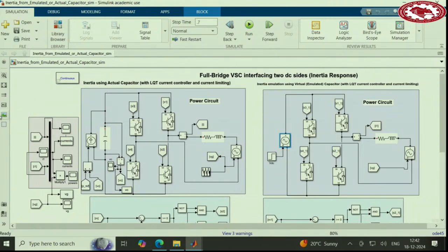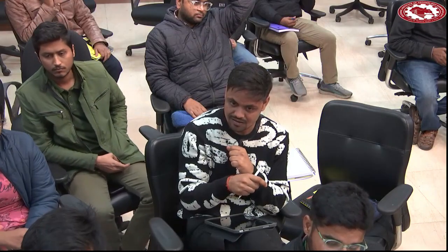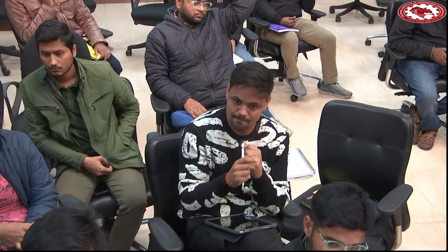If a DC link is there, with PV, DC link and then inverter, and the inverter is providing grid support, and the inertia I have chosen is very, very high, so voltage is going down, it has to supply the energy. If the DC link is not capable, the PV is not capable, what will happen? Will the DC link break down at that time? Yes, if the voltage goes below the limit, the protection part will shut down the converter.